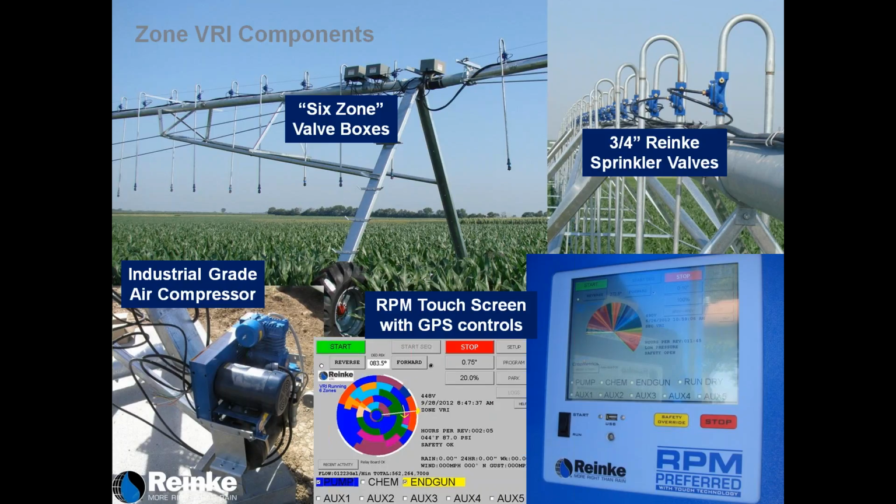Each of those boxes controls 6 zones, and they're all controlled by air rather than water, because air gives us a much quicker response than water could due to the pressure differences. And also there are other benefits by using air as far as plugging and those types of things. So we use an industrial grade air compressor for that purpose.